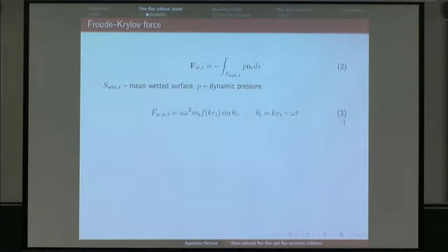So the force from the incoming waves is calculated by definition, so to say, by integrating the dynamic pressure over the wetted, submerged surface of the ice floes. And when we use the pressure from the linear wave theory and do the integration, we obtain a very nice formula, nice in the sense that DEMs like this kind of formulas that can be evaluated based on variables in the middle of the floe. So it makes everything very simple from the practical point of view.